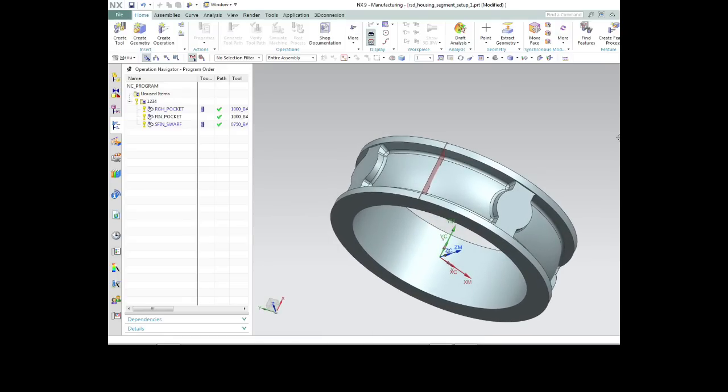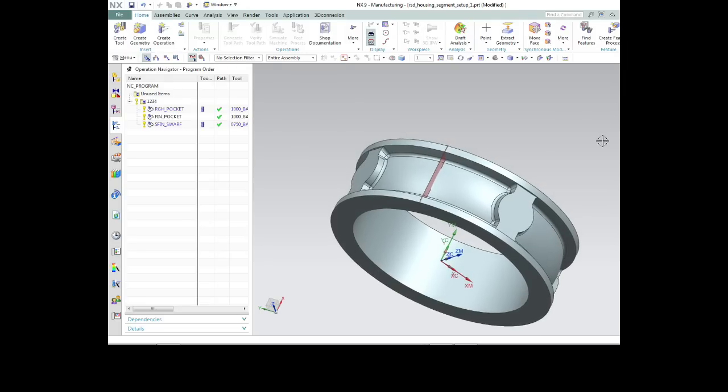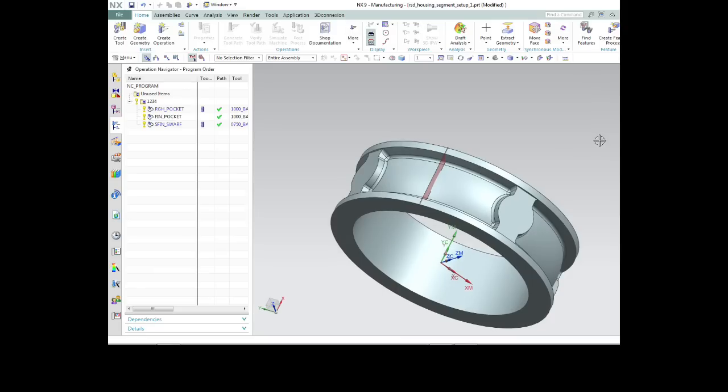And it's all about part surface, drive surface, and check surface. I don't know if you've ever programmed in APT, Automatic Part Tool Programming Language, you'll be really familiar with part surface, drive surface, check surface. Part surface is where the end of the tool goes. The drive surface is the surface that you want to drive with the side of the tool, and the check surface is where you want to stop with the side, the center, whatever.